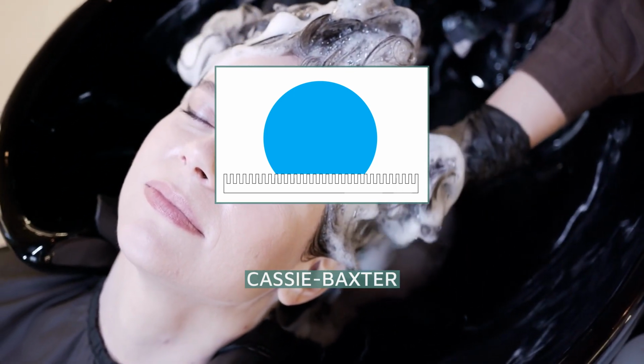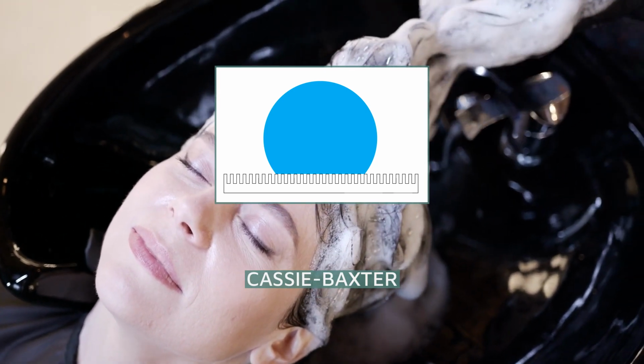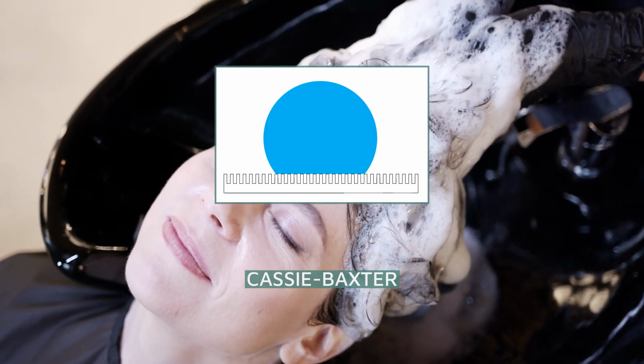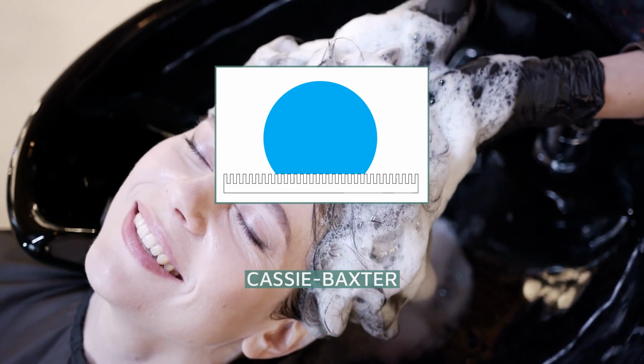Experimental results regarding the surface properties of Wenzel versus Cassie-Baxter systems showed the effect of pinning for a Young angle of 180 to 90 degrees, a region classified under the Cassie-Baxter model. This liquid/air composite system is largely hydrophobic.